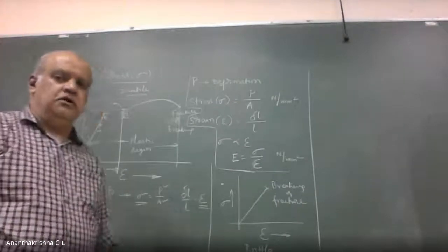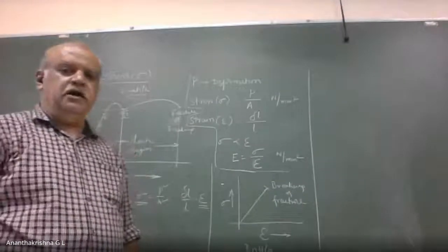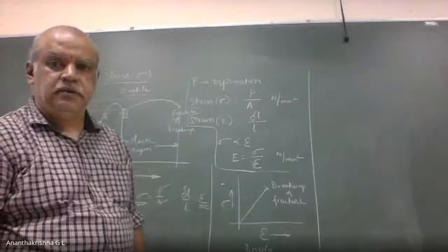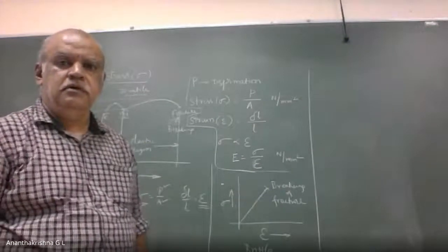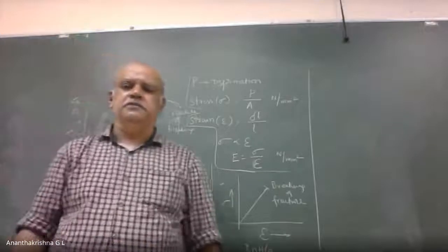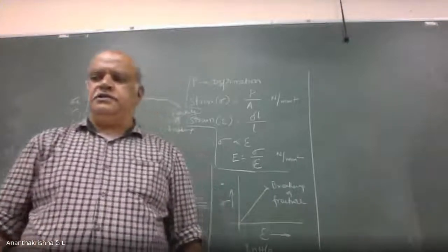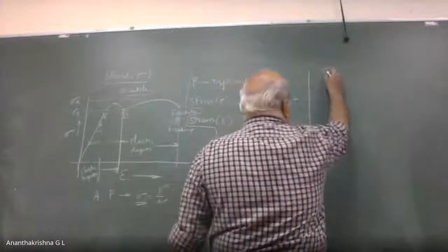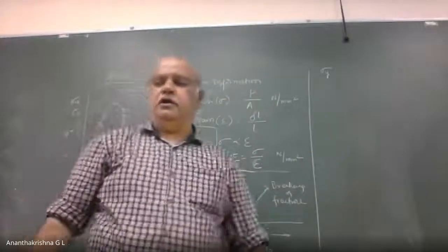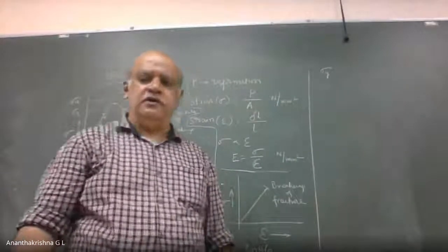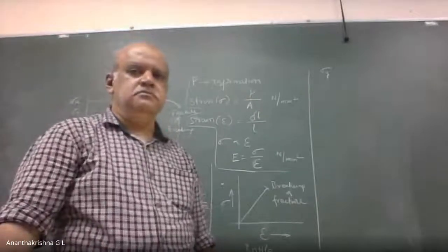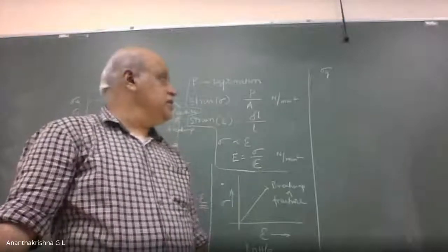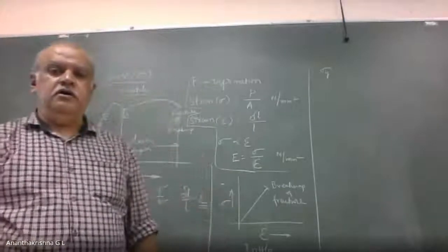Please note down. For ductile materials, yield stress sigma y should be taken as reference for designing a component.